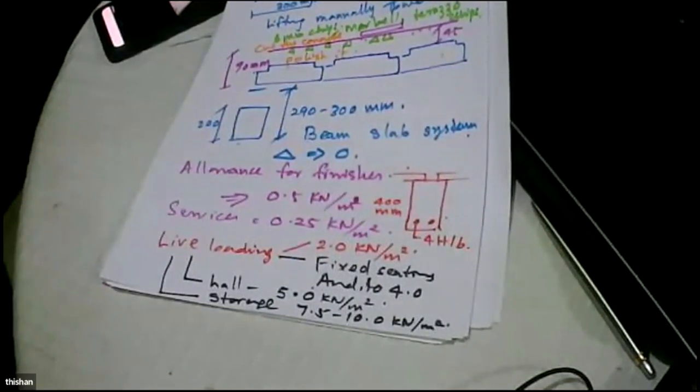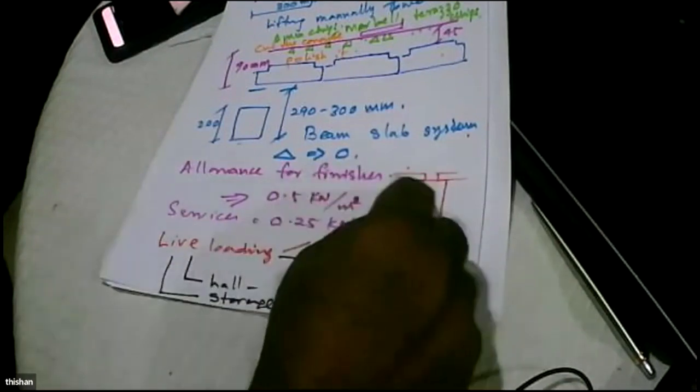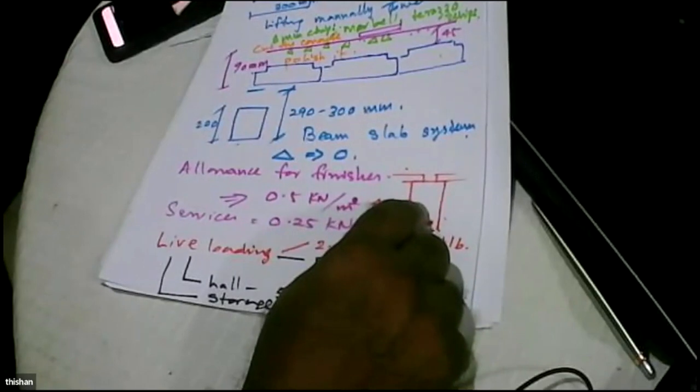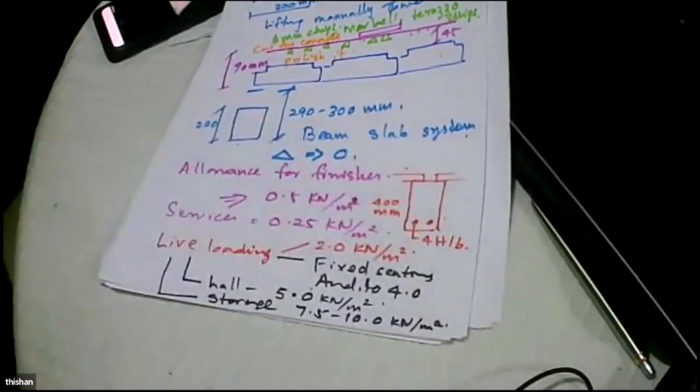And then there's another trick. You think this can be overloaded. What we can do is, for this beam we can have another span, but they are cast as simply supported. So at the site, we can make them continuous. So there are many options that are practically possible.